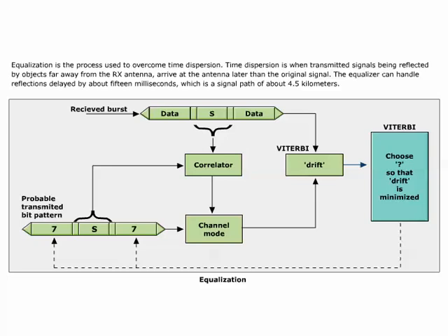Data is transmitted in bursts, which are placed within time slots. In the middle of the burst, a training sequence of a known pattern with good autocorrelation properties is established. This training sequence is used by the equalizer to create the channel model. This model changes all the time, but during one burst it is considered to be constant. Rayleigh fading, due to near-region reflections, influences the reflected signal. This signal has an independent fading pattern compared to the direct one and can be used by the equalizer to enhance performance.